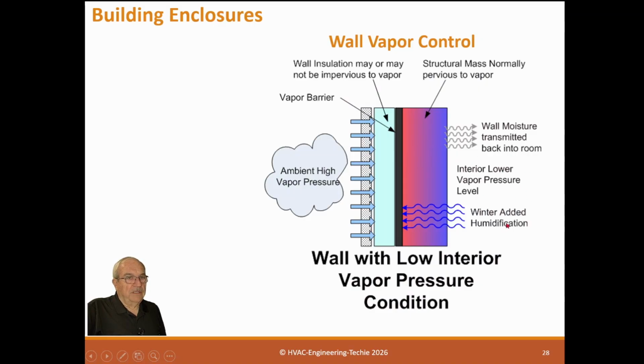So if, during the winter months, we get added humidity, it will come and sop into this wall, but it hits this vapor barrier, and then it redries. When this is lower, it redries into the space. So there's not a mold issue here, because the water comes in and then it goes back out. Here, the water never gets in the first place, so that's good.